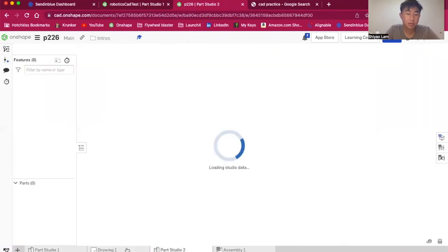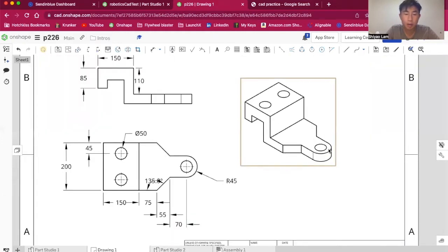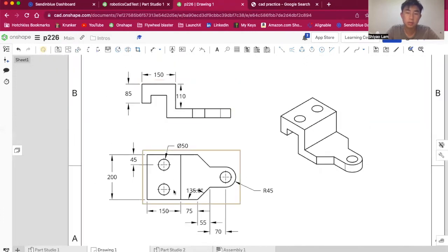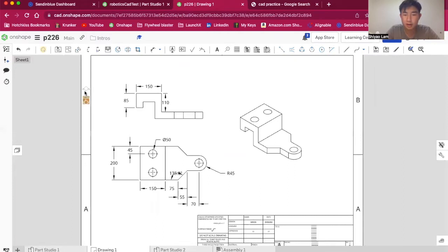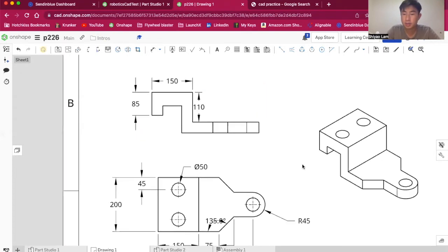But you can select multiple faces that you want to start from. For example, you can start from the bottom of this piece, on the base, and CAD it upwards, or you could take this side pattern. These are two equally valid ways in which you could CAD it. If you remember from the previous video, everything starts from a 2D plane. So you're going to have to start a sketch from some plane. In this case, you can start from the side and CAD out this question mark looking shape on the 2D plane. After you CAD that, you can extrude it and make those adjustments to make it look like this.